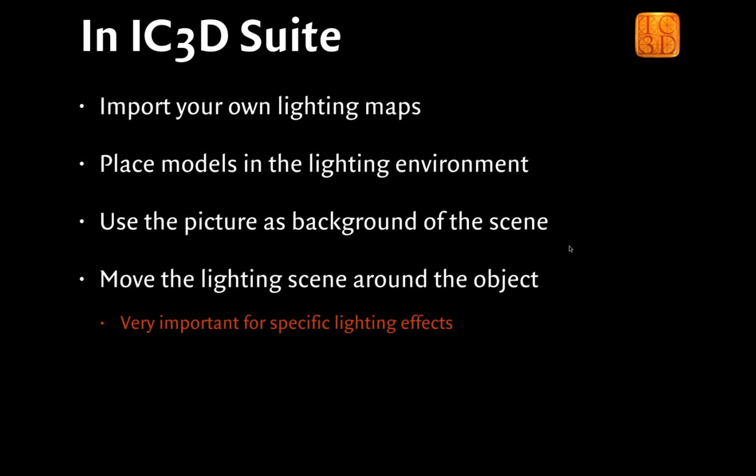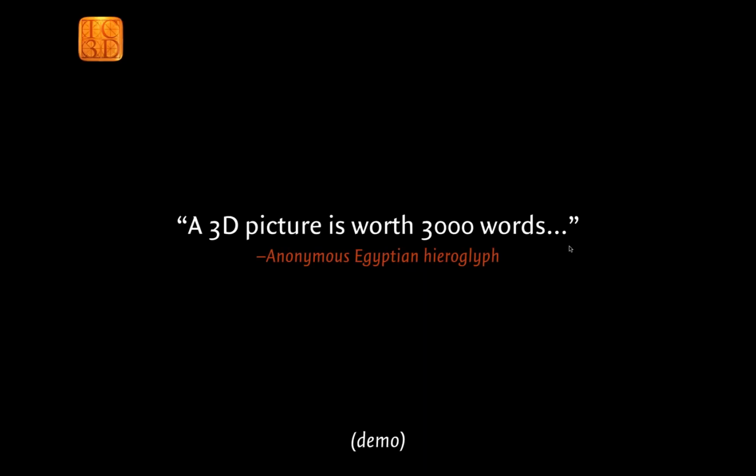Well, first of all, you can import your own lighting maps and environment maps. I already said that. It takes a long time to import them, but it's a one-time thing to do that, and then you can use them very, very quickly. You can place, of course, models inside of one of those environments, and you can choose in iC3D Suite whether you want to see the actual environment itself or whether you only want to use the light from that environment. Both are possible.